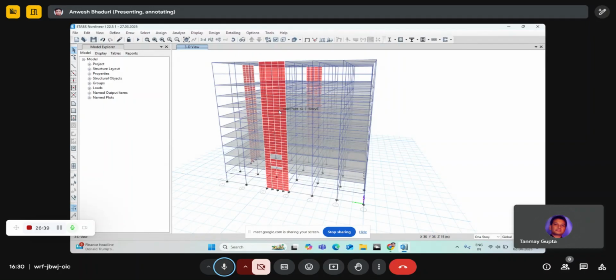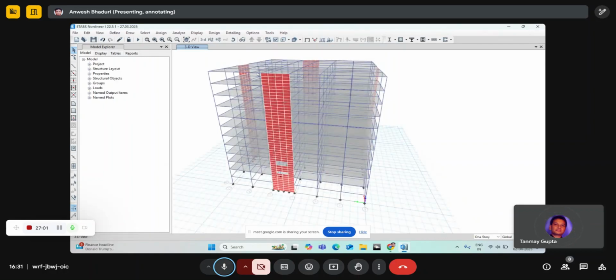As we are seeing displacement of story, can displacement of shear walls be seen as a line diagram? No, we have to see plate by plate, element by element. If we need to see the displacement of the shear wall only, actually now it's a combined system, so you'll get to see the displacement of the entire building.